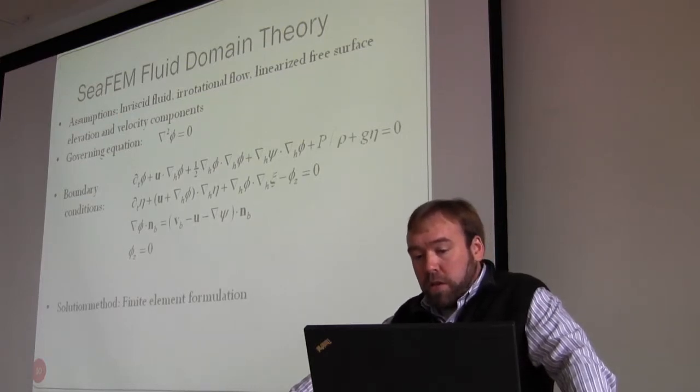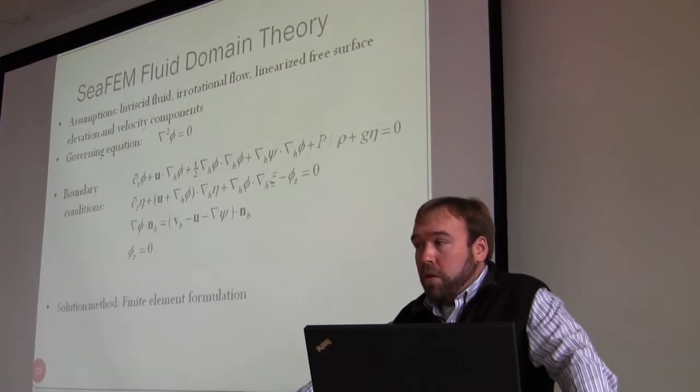Third equation is the body, rigid body boundary condition, and then the bottom boundary condition, kinematic bottom boundary condition is the last equation. And then this is all solved with FEM. I think I've said that 3 times now. So we'll go through a real quick FSI example of how CFEM can give you really nice results, especially for the structural modeling side of it. We'll consider a commercial yacht design.